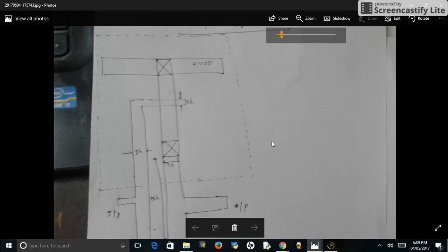We know how to fabricate PMOS and NMOS. For the PMOS, the substrate is N type, so here we take N well. This is the N well. In the N well we have to design the P type MOSFET. For P type MOSFET we require P plus diffusion material. So this is the P plus diffusion material. Size of the P plus diffusion material is 4 by 14 lambda, means minimum width is 4 and minimum length is 14 lambda. In the PMOS, the upper terminal acts as a source, below this acts as a drain, and this acts as a gate terminal.